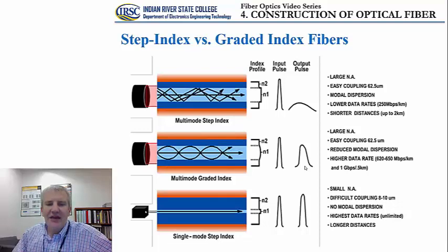The reason for that is the way different modes are propagate in the glass core. In the case of a graded index optical fiber, keep in mind that here we are talking about an index of refraction that is changing radially as you are moving from the center of the core towards the edge of the core. So it's almost like having different layers inside the glass core,